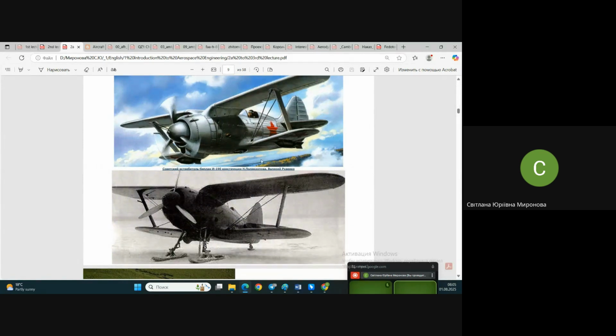So what about its characteristics? Look, a biplane, a strutted biplane. There are a couple of wire braces here also, but mostly it is a strutted biplane with a half wing. It's a so-called semi biplane. You see, a short low wing and a high top wing, but it's not only high. That is a decision which is called gull wing.